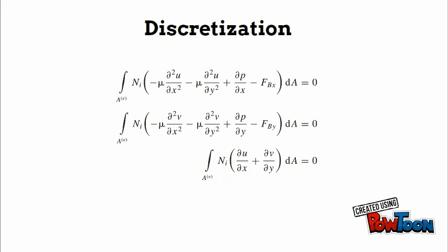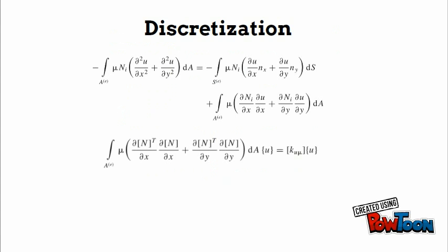We will now substitute in the interpolated formulation to define the integral form as an interpolation from each node. This will allow us eventually to perform the integration without knowing anything about the velocity or pressure. Green Gauss will be applied to the viscous terms, which we will have to treat as a black box since there is not time to explain.